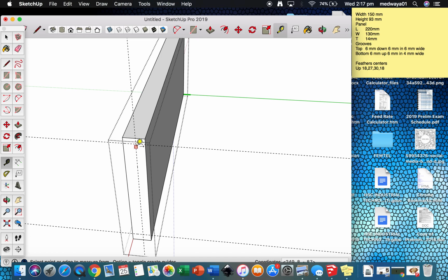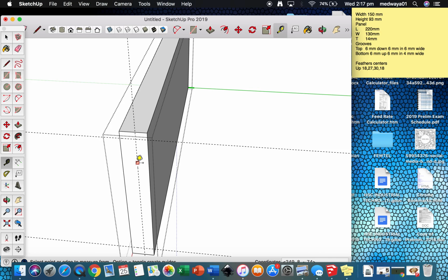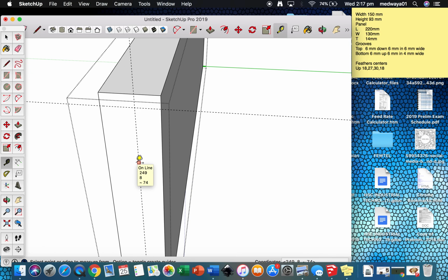So I've laid out a corner to start with to draw the rectangle. So I'm going to zoom in, and to zoom in, if you're using the Pro version, 2 fingers on the trackpad, slide up and you'll zoom in. If you use the online version, it's the opposite way, 2 fingers on the trackpad and sliding down. So I'm going to start from this corner over here. So I'm pressing R for rectangle tool.